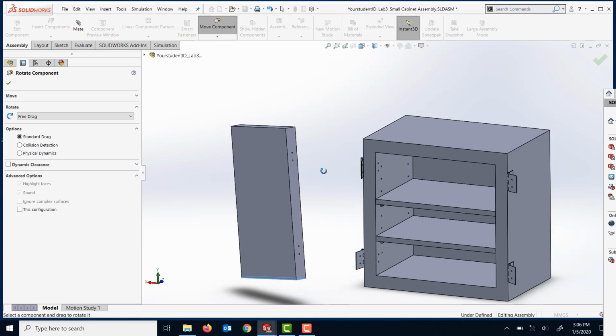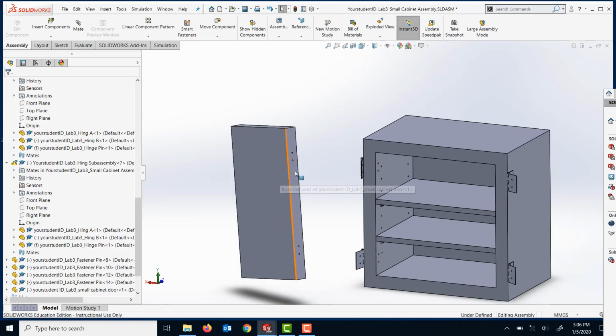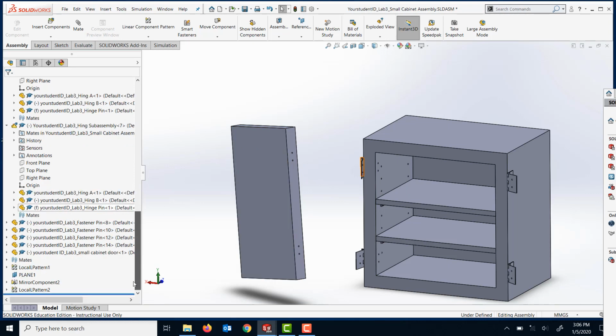So one thing that I know, the fastener pin that is installed and the hole size, this is not deep enough. So I'm going to change the size of those holes in this assembly environment, and it will be saved down there.